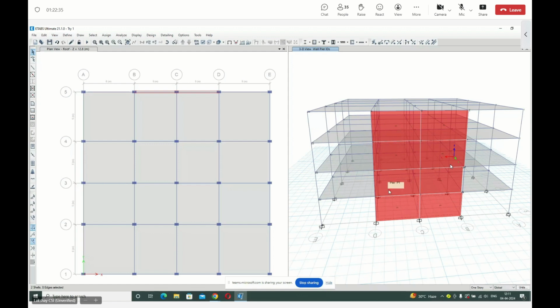So we'll again select all the walls. One way is selecting again and again. For example, if you want to reselect something that you have recently selected, I'll select all these walls. I selected right now 8 shells and 32 edges, and I want to select these again. I've unselected them. I'll go to select and click on get previous selection. The program will select those walls automatically.